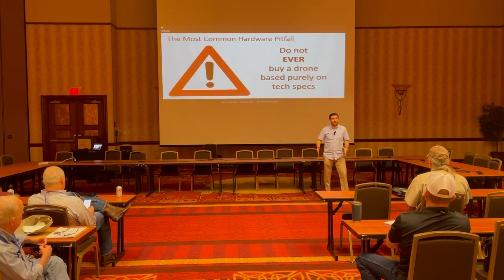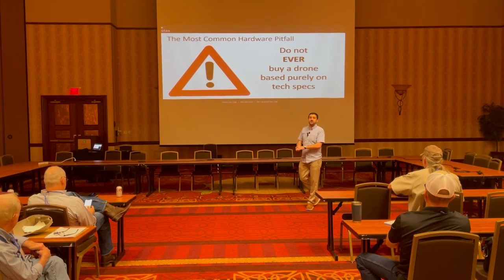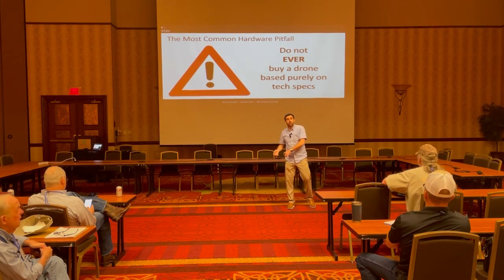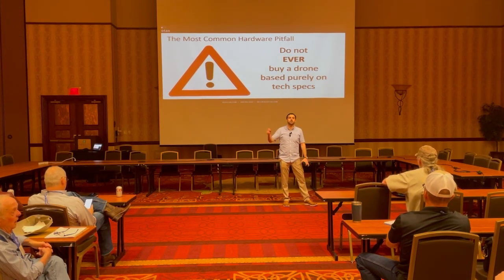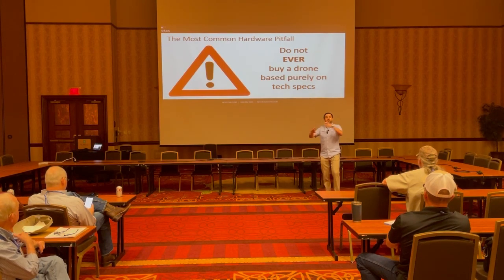That's not the difference between a good LiDAR project and a bad LiDAR project. A good LiDAR project is one that works, and a bad one is where a super complex drone didn't have exactly the right field setup, so it didn't log the RTK at the right clock base, and it won't sync with the PPK so that you can't process the data at all, and then it's worthless.